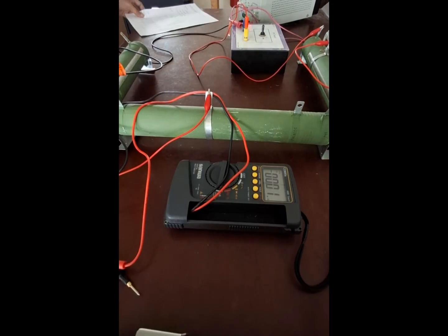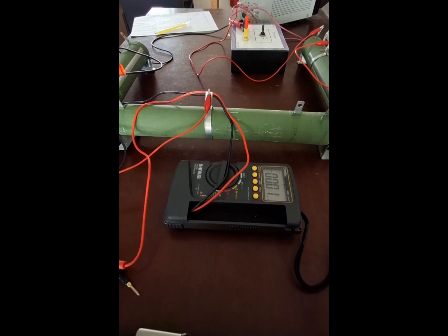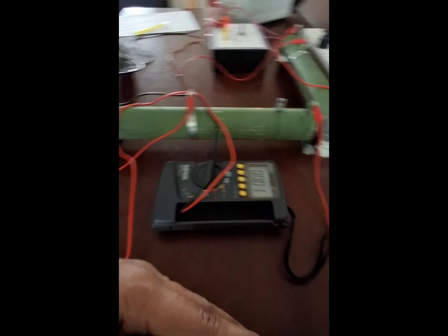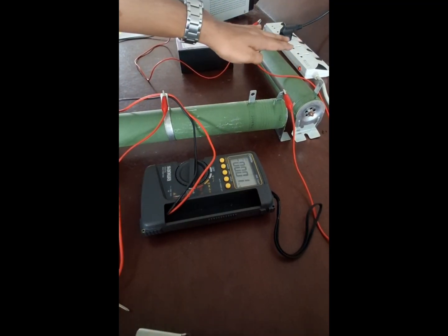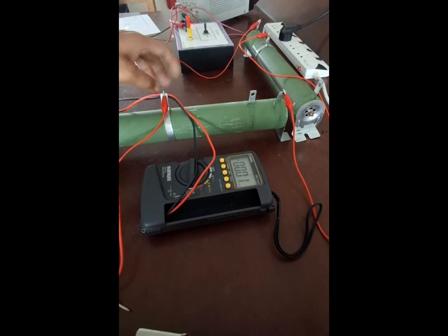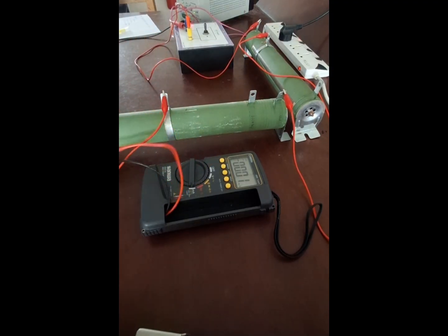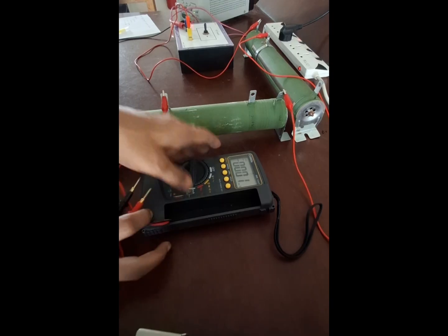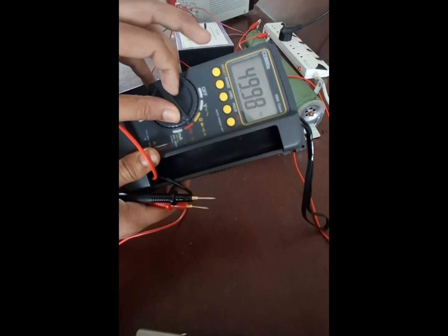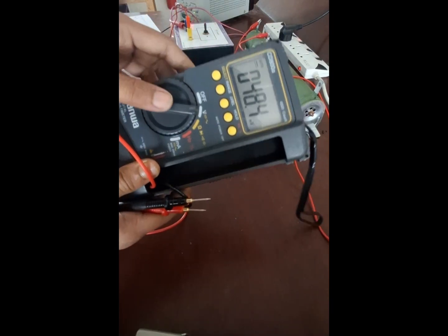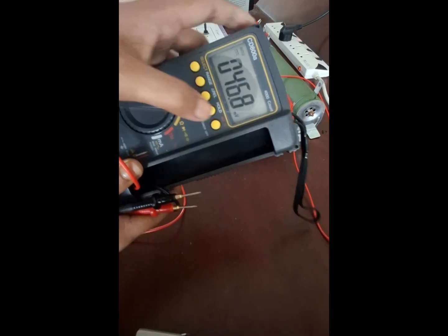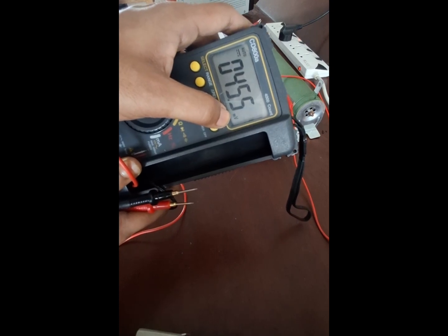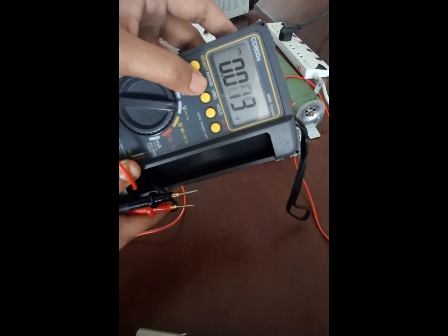Okay. The second thing we will do is measuring the voltage across the three resistors we have here. So the first time we will measure the voltage across this resistor, that we take as resistor 1 or rheostat 1. So we will measure the voltage drop across this rheostat. So for that we have to take our multimeter to voltage, and we have rotated our knob to the voltage measurement parameter. Now we see that our range is millivolt. We will change the range from millivolt to volt.